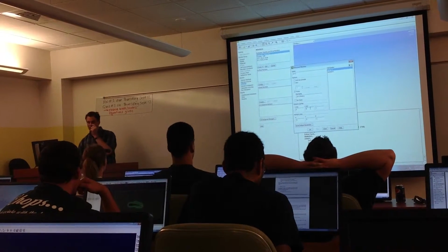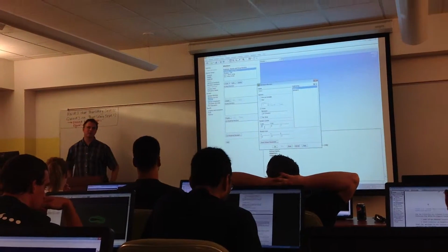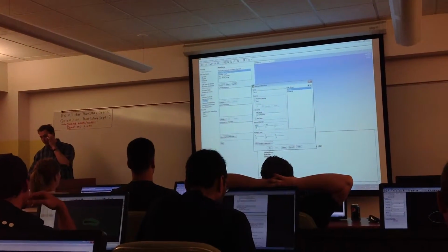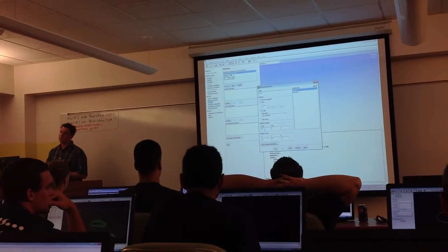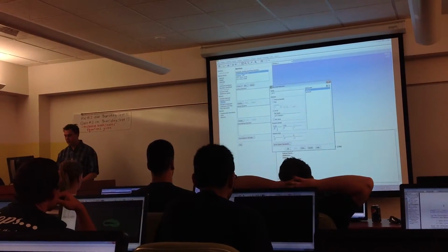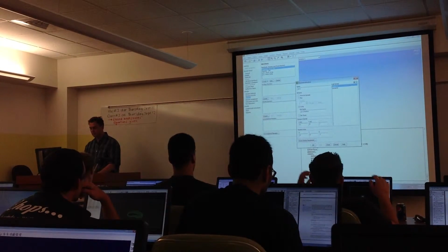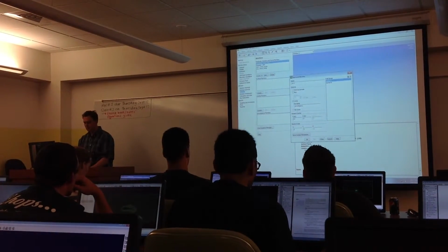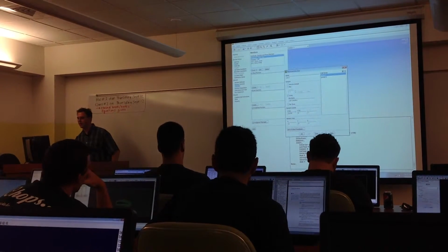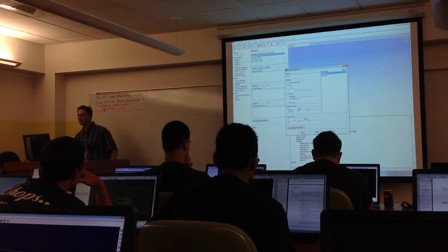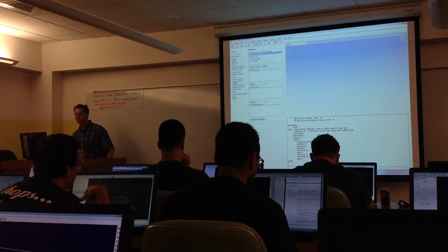Now, where's the moment center? Usually, if you're going to compare to actual airfoil data, it's the quarter chord. So it would be 1/4 of the distance from leading edge to trailing edge, roughly speaking. So in this case, 1/4 of 0.3. So 0.075, right? Ish. Right. Okay, and the moment axis would be the Z direction, Z out of the plane. All right, so we have those monitors set up.